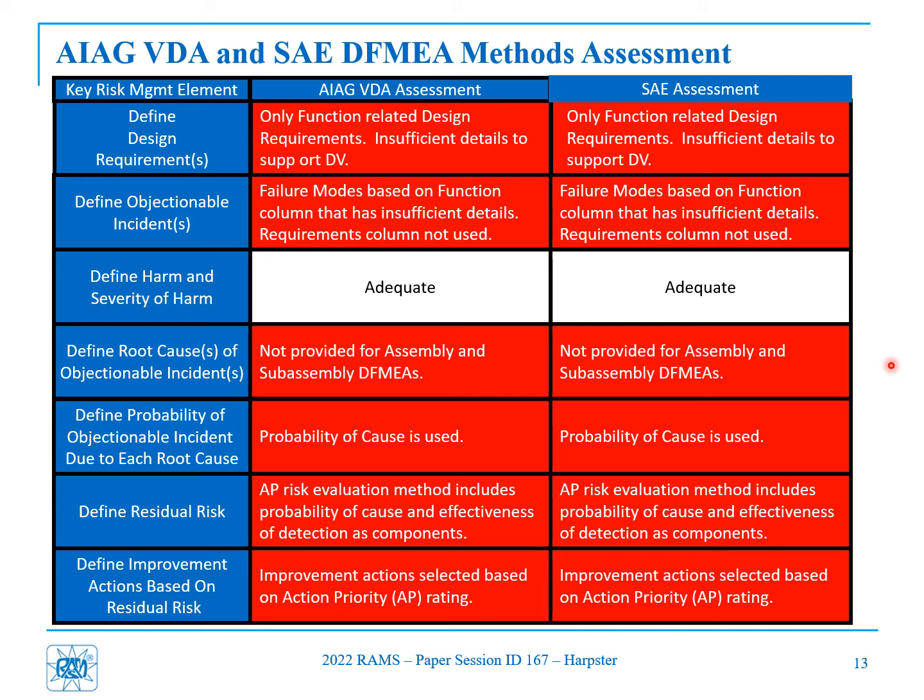And when you have a subassembly design FMEA, the failure mode cause is some form of component failure. It's only when you have a component failure that the failure cause is in the form of a characteristic spec and a condition. So what we see is that the system FMEAs and the subassembly design FMEAs created using both the AIAG-VDA and SAE FMEA methods result in failure modes being put in the failure cause column.